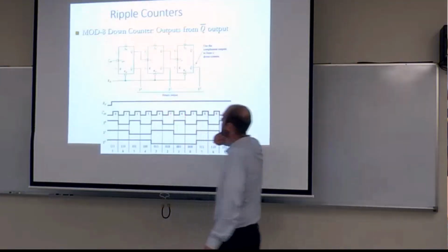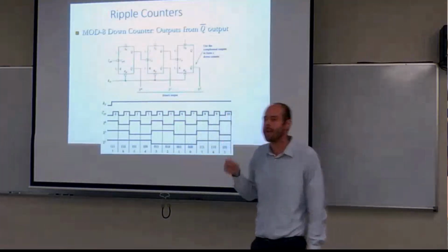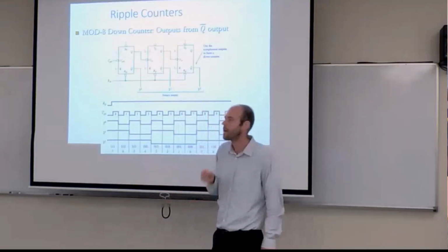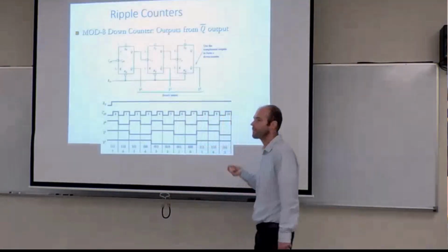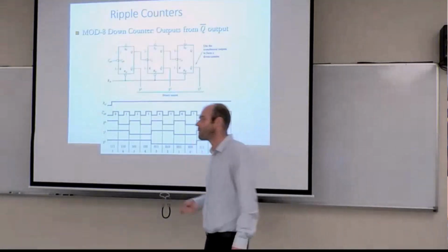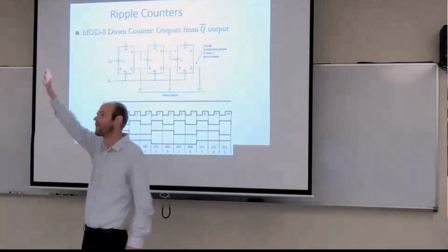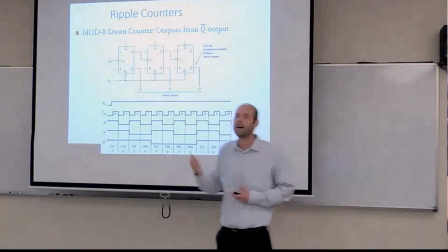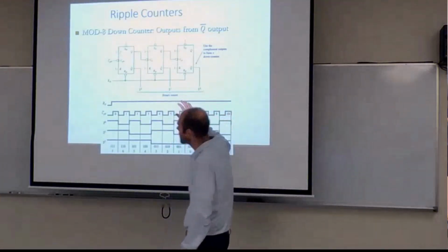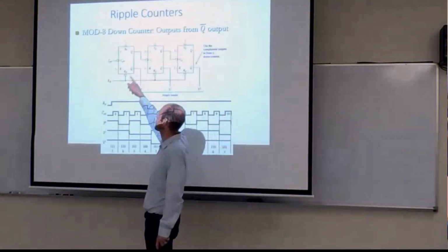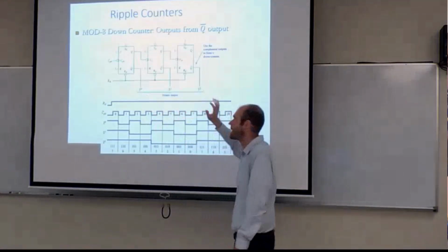But we can use the very same counter circuitry that we just defined to count down as well. So if you've ever been to your favorite fireworks show and you want to count down from 10 to 0 before everything launches, we know counting down has utility as well. We can count down with our circuitry by just using the Q0 bits and using the rest of it identical.